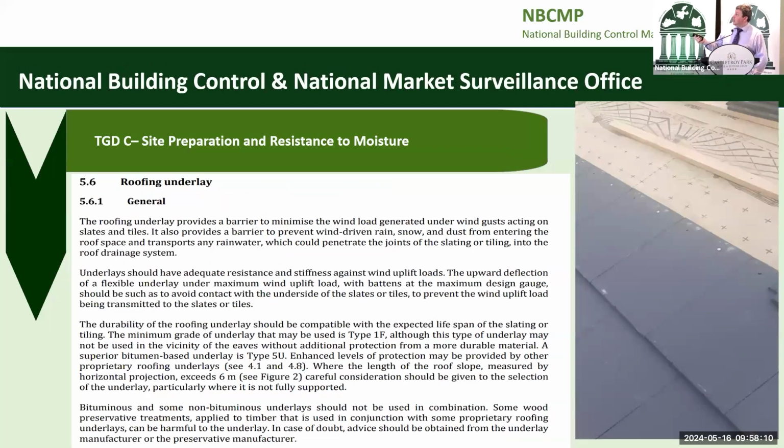There are usually 2 holes in a tile, but you only have to nail one of them, and that's so you can split them. Generally, a couple of years ago, it was every 3rd row that had to be nailed. Now it's every 2nd in moderate areas. If you go into severe, you're nailing every slate and you're clipping in as well. And Aidan will go through that later.